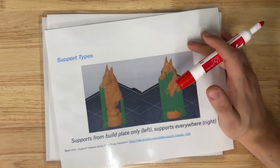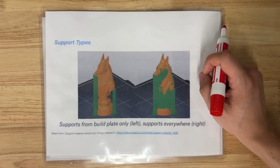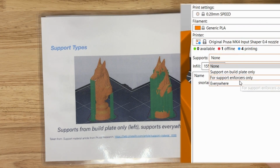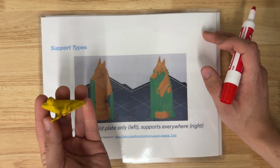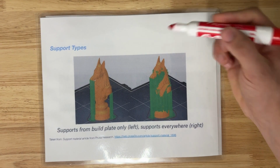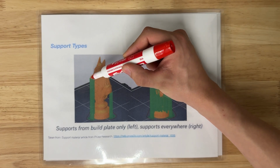It's not always easy to tell if you need supports on your print. Usually in the description, wherever you downloaded it from, you can read if someone advises you to use them or not. We always want to try to print without supports. These frogs were done without supports pretty easily. Our printers can support overhang up to a certain point, and then you're going to have to turn them on. In this case, this guy's nose would be floating up in midair, and we can't have it printing on nothing.